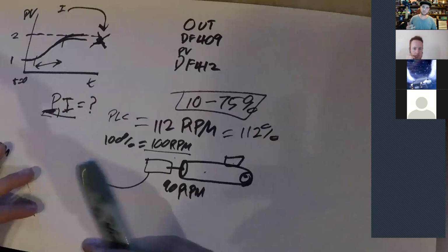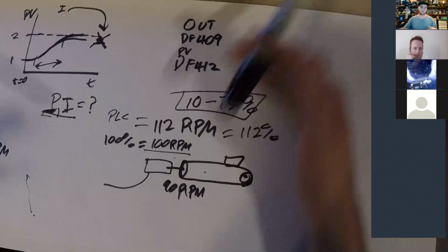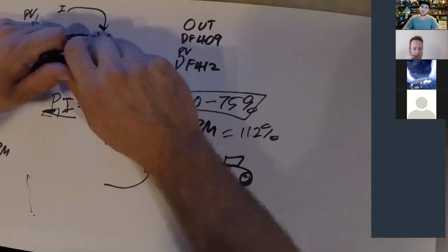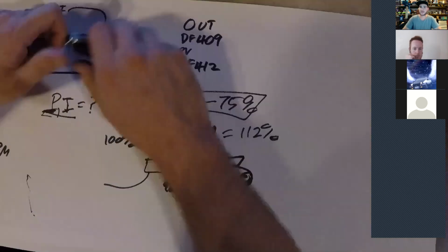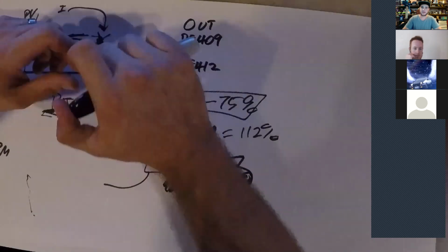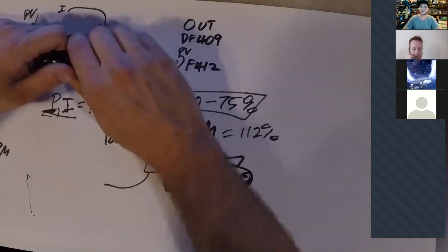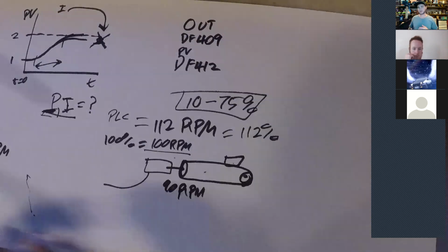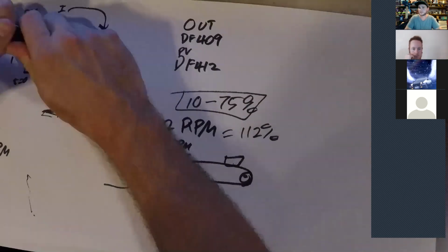We played with the P term for speed of response, and then we set the limits to the minimum and maximum flow rates that they needed for that application. But in terms of actually programming this on the CLICK, I played around with it before today, but this is probably the first cradle to grave PID implementation I've ever done, if that answers your question.